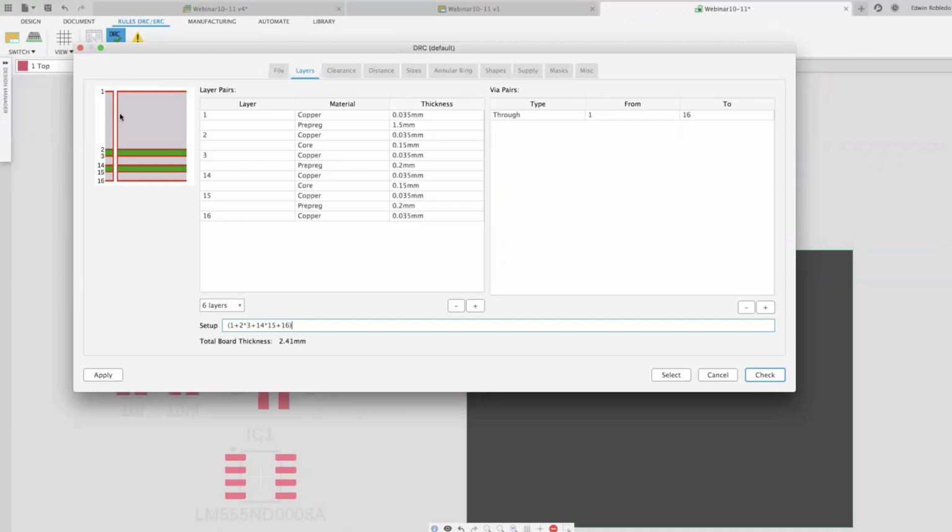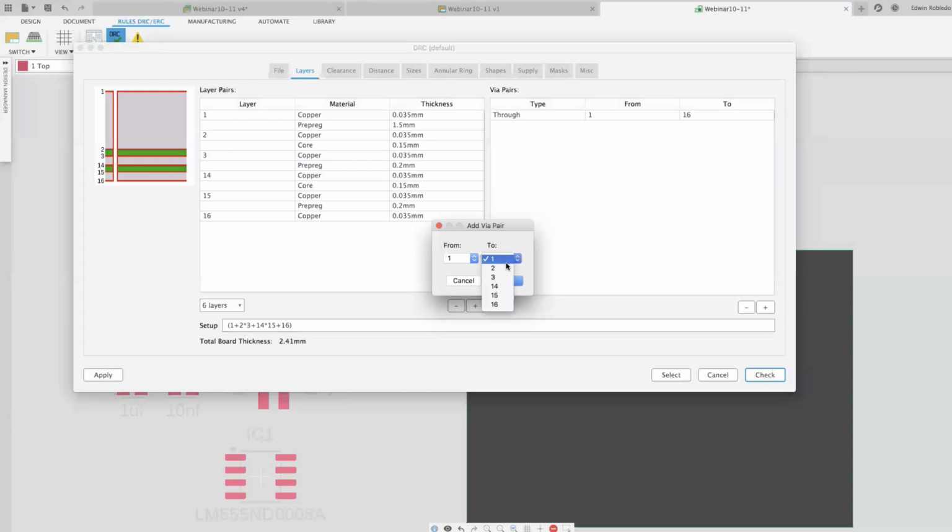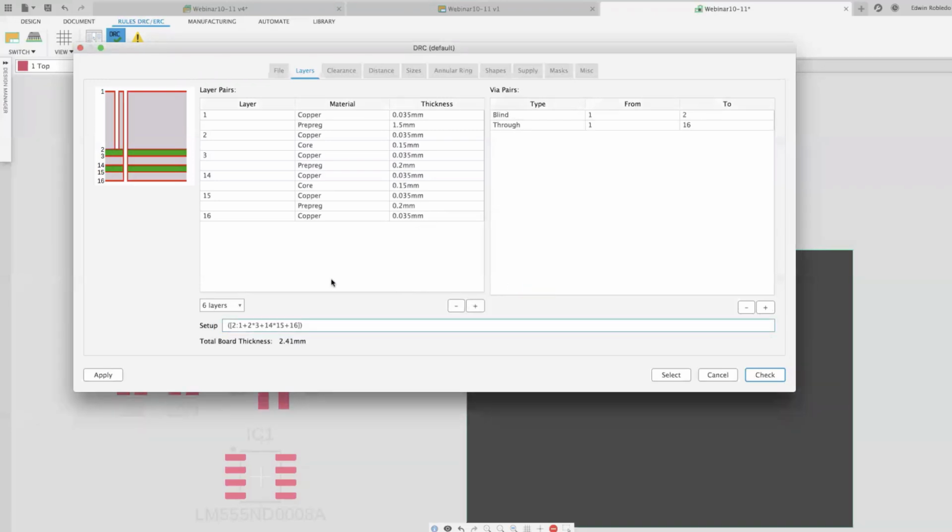And just for a practical consideration, typically this is the cheapest stack up you can get, when the vias go through the whole board. If you get more sophisticated and have vias that only span certain layers, then the price increases pretty dramatically. So if you can, you want to try to make your design using just through hole, because if you have any type of depth controlled vias, then things become very expensive. Some designs need it, but make sure yours is one of those. Thank you, George. Appreciate that.